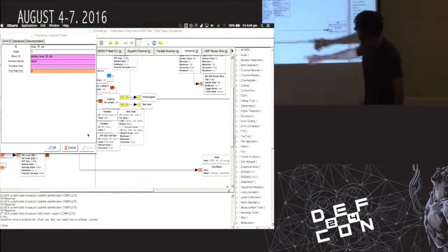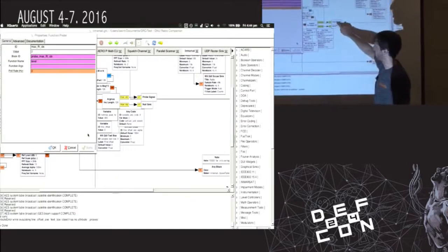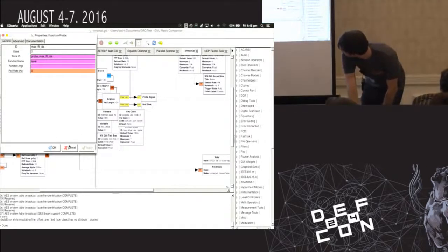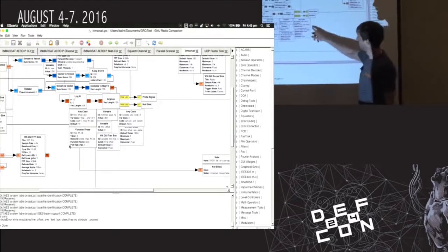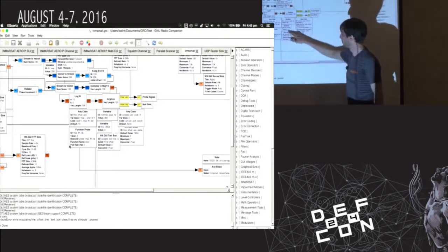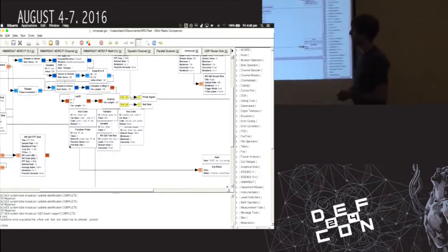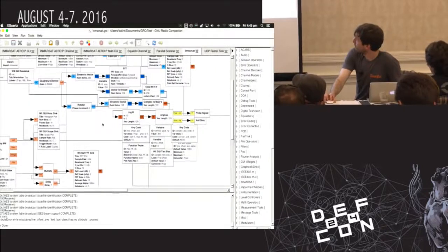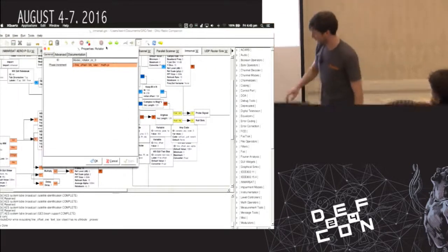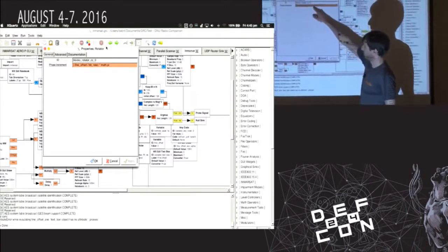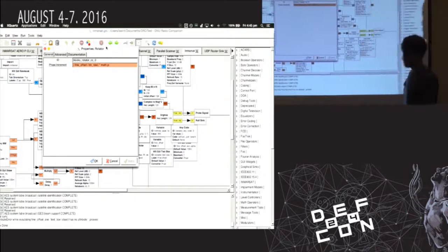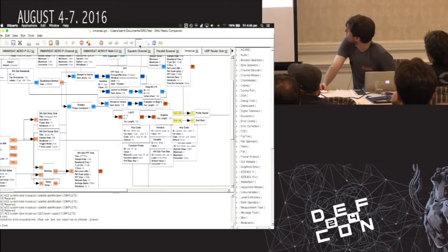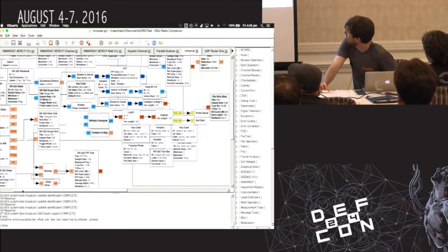And in function probe, it basically just calls level, which is a function that's exposed by probe signal, and that gets the index, I guess 5 times a second or something. And then when it does that, you put it through one of these variables, and then it calculates that as a frequency offset, which is then fed back as a variable into this rotator. So it takes the fine offset divided by the baseband sample rate, and then multiplies it by pi, and so it shifts your baseband around, so it lines it up. But that wasn't so good because of those obvious issues I pointed out.